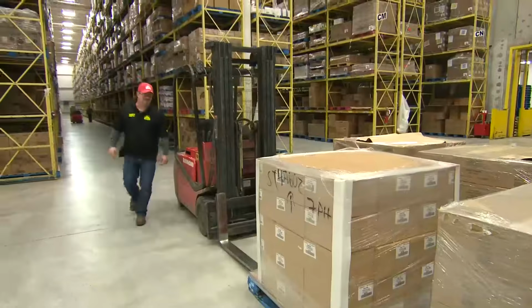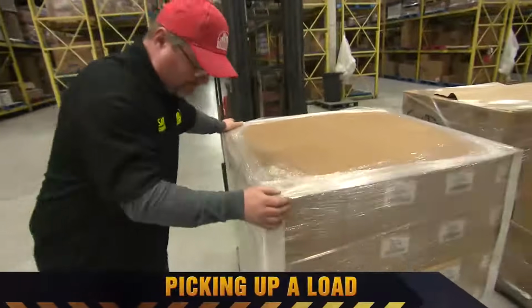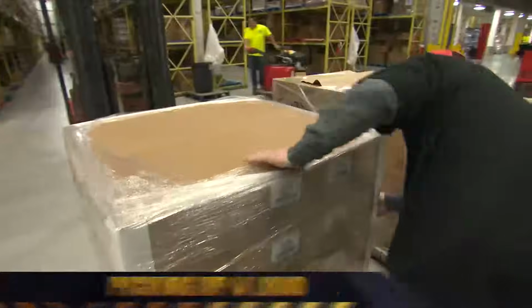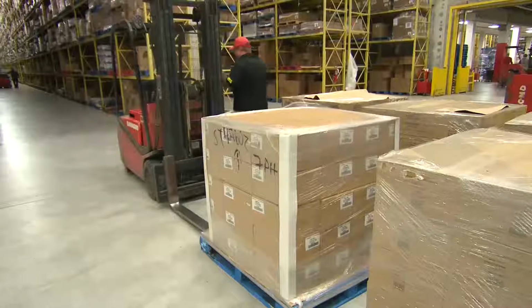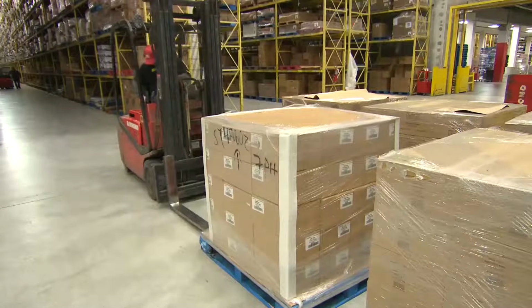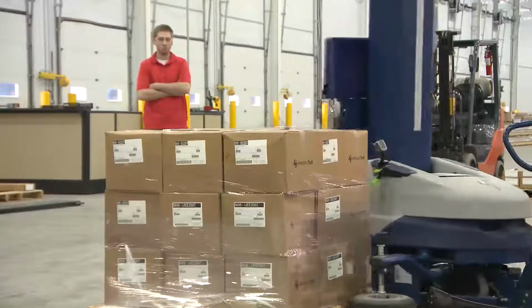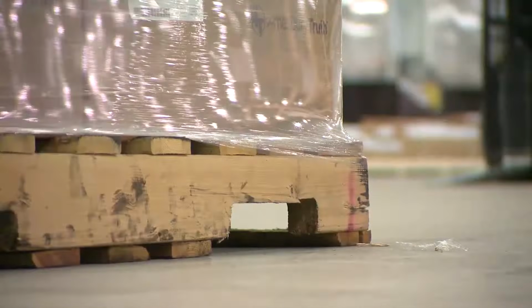Before you pick up a load, make sure you know exactly what you'll be lifting. There's a big difference between a light centered load and a heavy off-center load. Confirm the load is within the capacity limits for the forklift. Is it balanced? Will it be secure? If the load is unstable, restack it or attach the load securely to the pallet with shrink wrap.